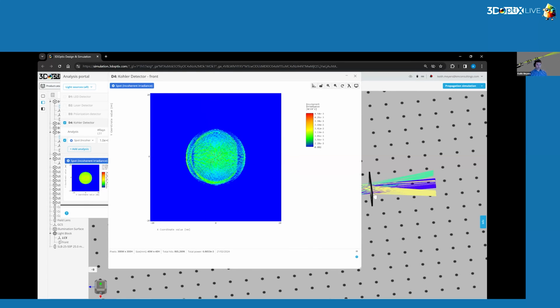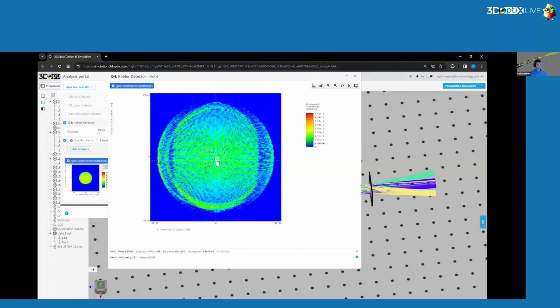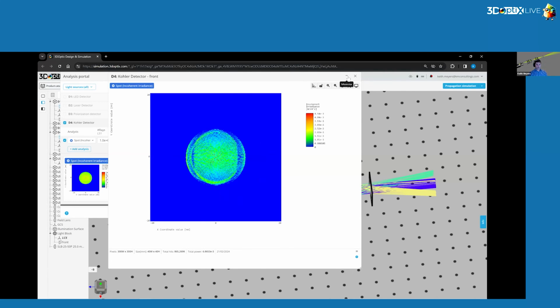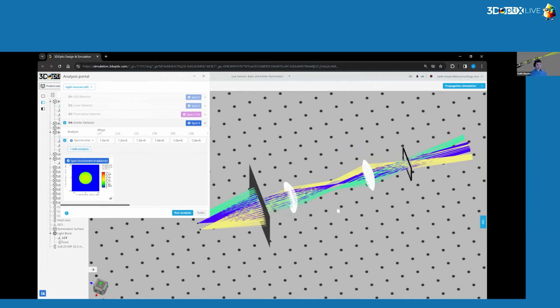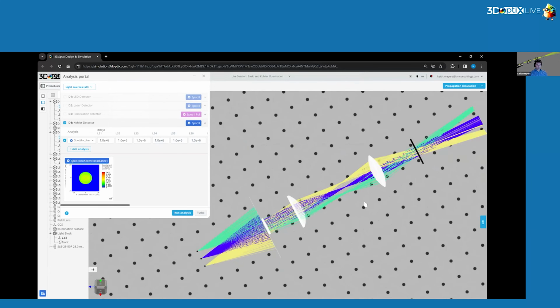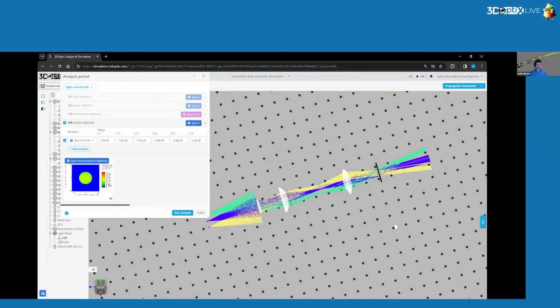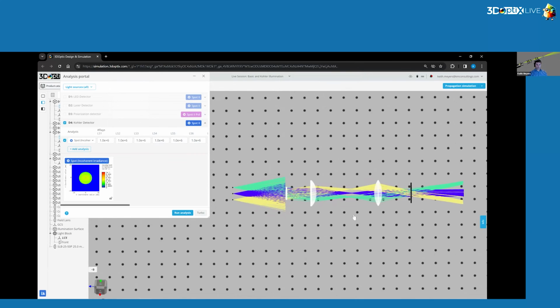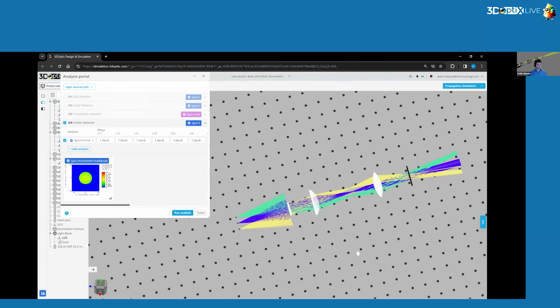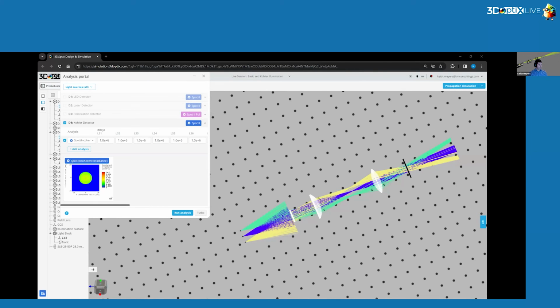So this is a good start. We could definitely move the detector and the optics around to increase the homogeneity of this illumination profile and get a very even illumination at the target plane. Now this is a good start, and we would want to optimize further from here. I'd also like to point out that because we are using refractive optics, there will be some chromatic aberration here, so you'll see a halo effect here. By using an all-reflective system, if you can get the same Kohler illumination, then you would rid yourself of chromatic aberration. So it looks like I'm out of time, so we'll stop there.